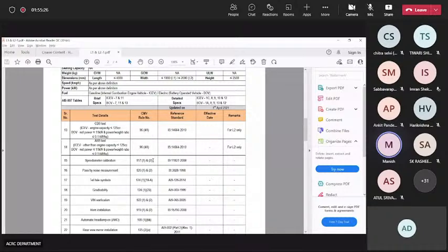It is defined under AIS 126. So what kind of telltales you can use in your speedo cluster, whether it's a dashboard or speedo cluster in two-wheelers, is predefined by agencies for homologation. The same symbols have to be used in your cluster. You cannot make your own symbols for anything which falls under the telltale category. That has to be kept in mind, and they will check that part in your cluster.